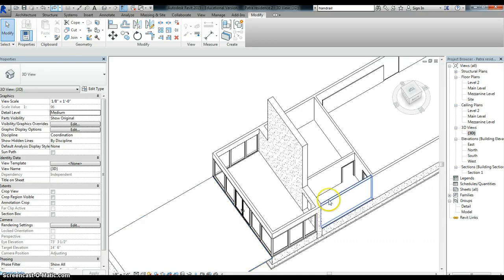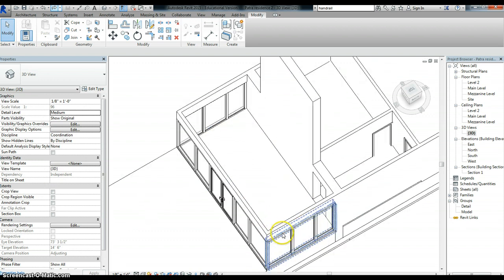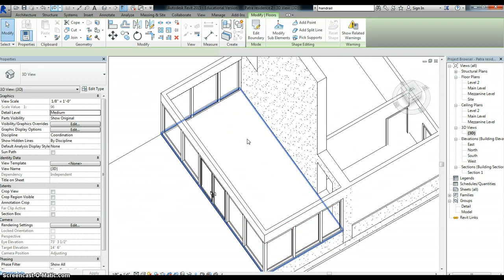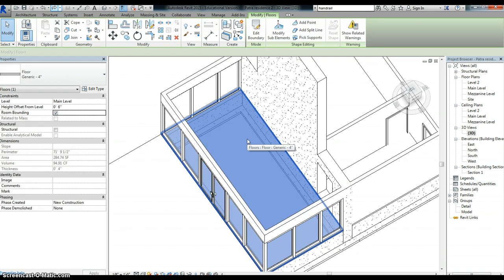I've got this beginning with showing the lobby, so I know you can shut off some layers so that you can do this. One of the things we're going to do is start editing this slab, and one of the things I'm going to be using is measurements off that opening that goes through the concrete wall, and then working back to cut an opening in the slab, and then start to insert different levels into the slab so that you can have that base to start out with.